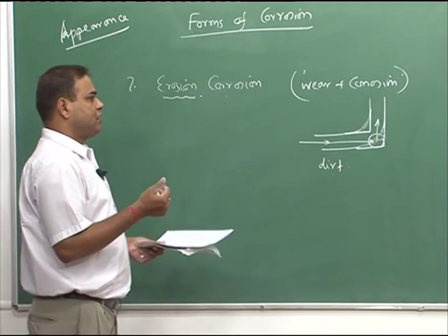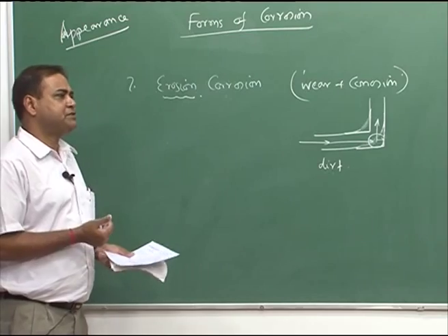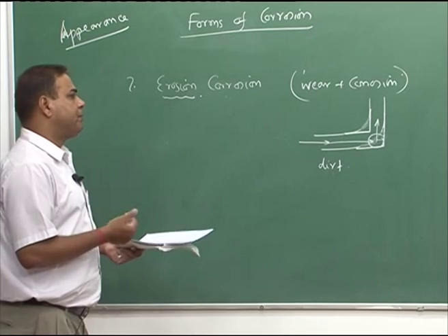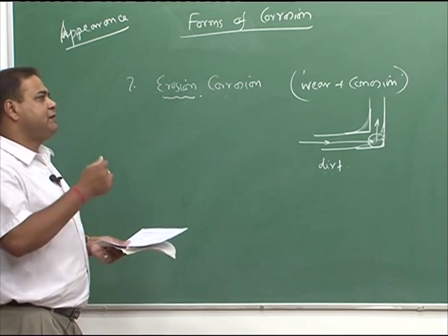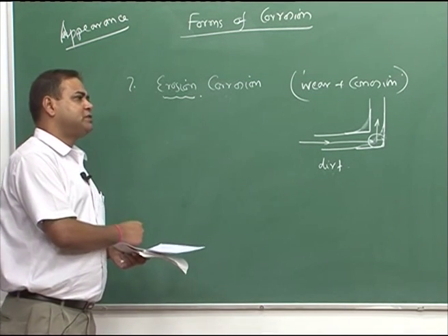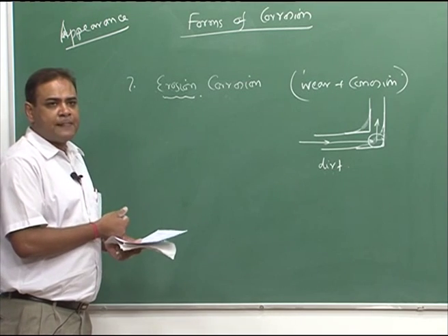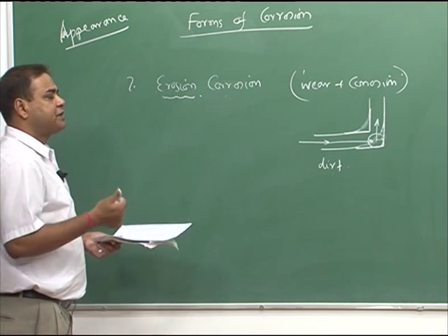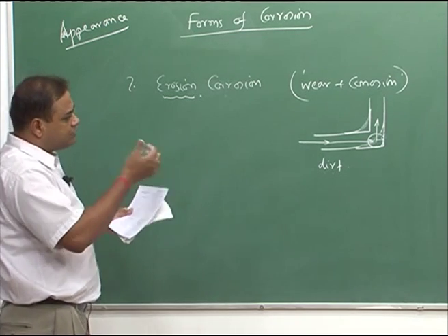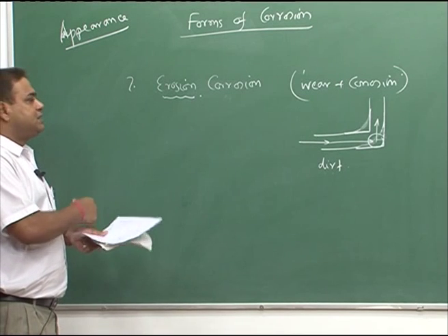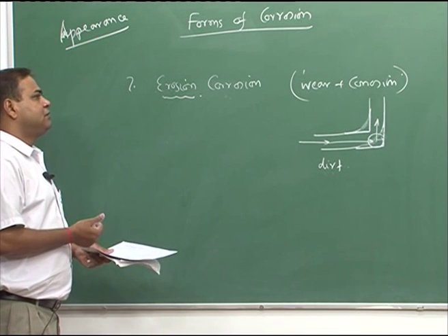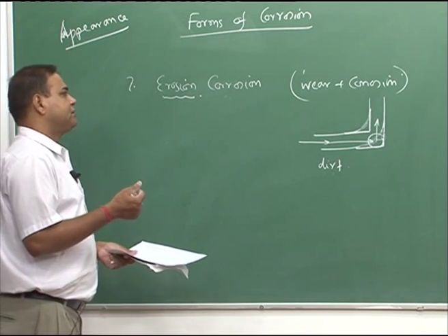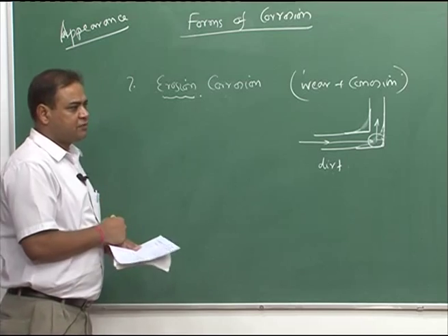Or it can arise if, let us say, there is a reduction in water pressure, then there could be a formation of bubbles, and if we increase the pressure of that water, the bubble will collapse. During this bubble formation, low pressure and high pressure creation, the bubble will form and then collapse again, and during this collapse process a huge amount of pressure can be imposed on the metal surface.